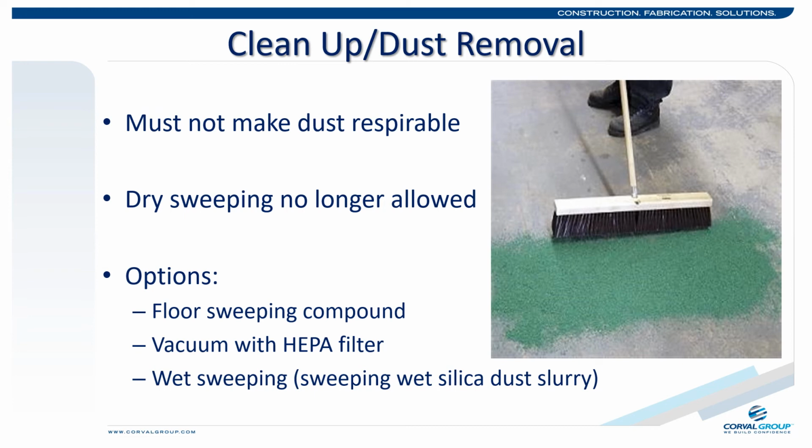OSHA no longer allows for the dry sweeping of silica dust. Dry sweeping not only puts the worker involved at risk, but any other person in the area, as dry sweeping creates high airborne silica concentrations. Ideally, tools equipped with integrated dust extraction systems should leave very little silica dust after the activity is completed. Should silica dust removal be required, an approved method should be used, such as sweeping with a sweeping compound or vacuuming with a vacuum equipped with a HEPA filter. A cleanup method should always be listed on the task's exposure control plan.